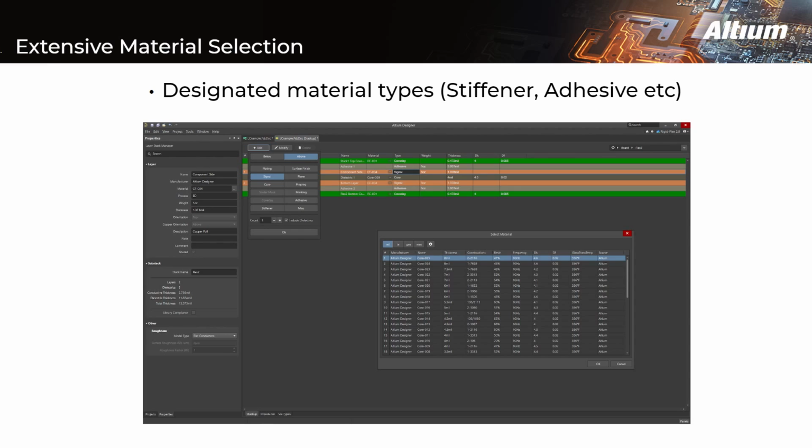Many Rigid Flex designs often require rigid stiffeners where flex tails plug into connectors and adhesive layers to attach multiple flex stackups together. This release adds a workflow for creating stiffeners and adhesives to enable creation of completely new types of Rigid Flex designs. We have defined a materials library for Layerstack definition, use predefined layers for flex stacks featuring their own specific behaviors and visual representation for a more complete and realistic physical model of flexible PCBs.